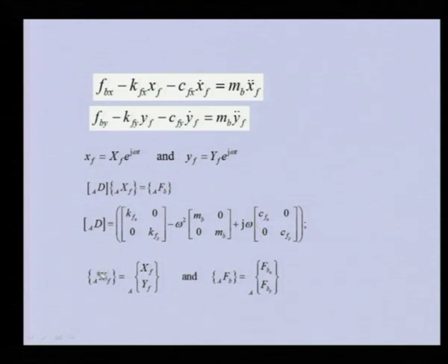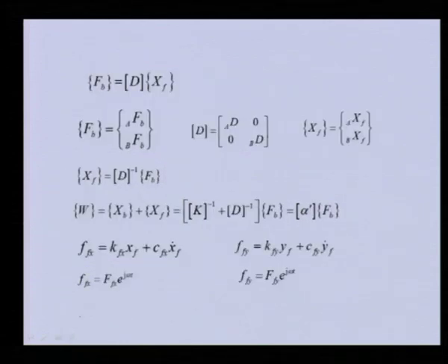Similarly, these are the bearing forces coming from the fluid film onto the bearing mass. So, this particular expression relates the bearing mass displacement with the fluid film bearing forces coming onto the bearing mass.